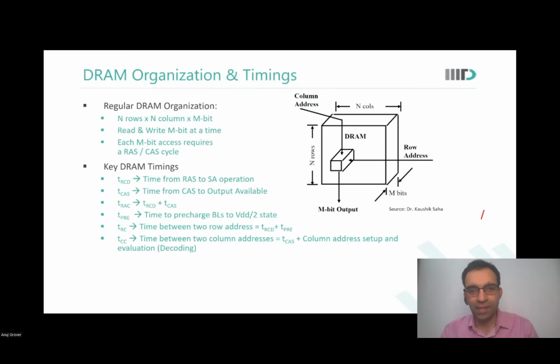So see, whenever you think of a solution, think of all three aspects: power, performance, and area. You cannot simply say that functionality has come, so it is done. As designers, you have to look at all the various aspects linked to the circuit. So think about it. We'll come to the answer in a little while. The answer would also be interesting. These are linked questions. How do you precharge the bitline to VDD by 2?